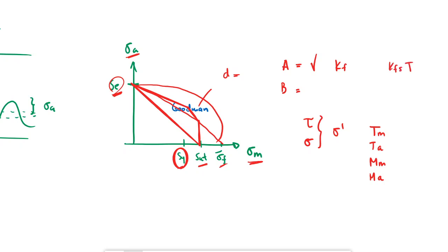Okay, for the torques, this would be alternating, moment alternating. I don't remember actually the values here, but something like this. And then for the mean moment, the same thing. That was just a generalization, so that you don't have to do this process every time and come up with the von Mises stress.